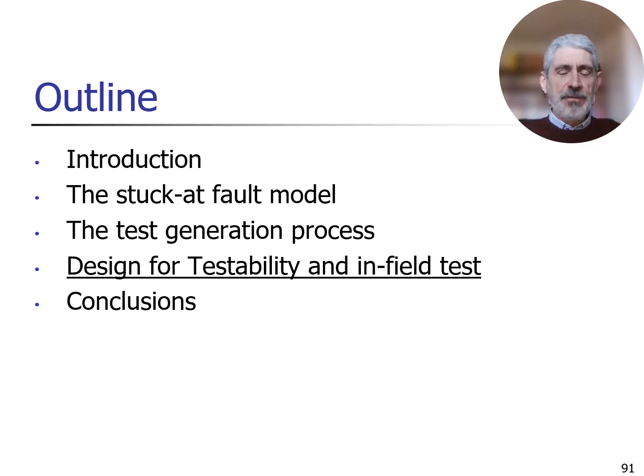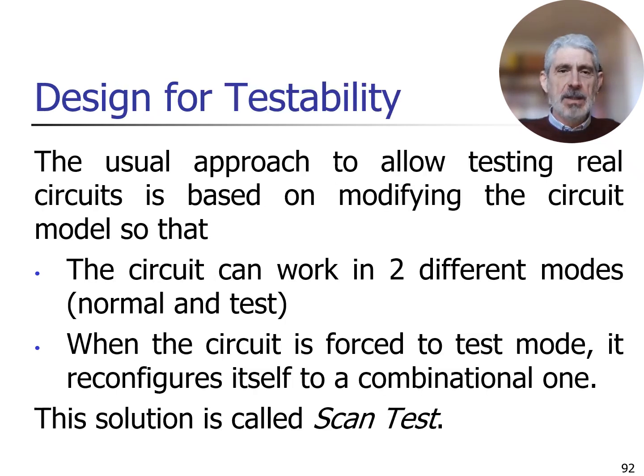So let's move to the fourth point in the agenda for today, in which I will introduce to you some key concepts about design for testability, scanning in particular, and I will say a few words about in-field test. Design for testability. The motivations were introduced just a moment ago. In this case, the main motivation was we are not able to generate test sequences for the generic sequential circuit affected by a stuck-at fault. So we need to modify the circuit so that we can test it.